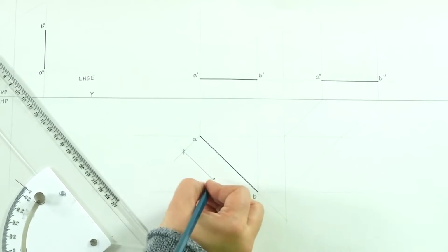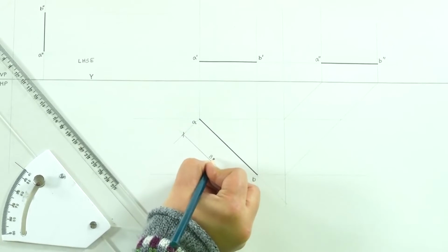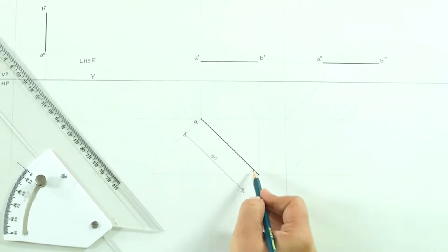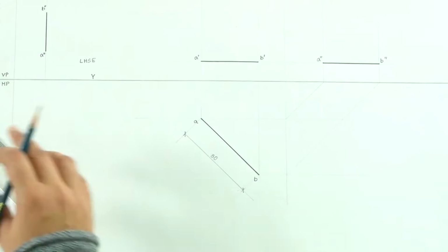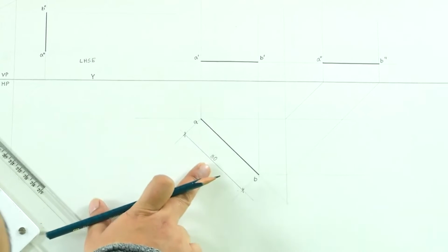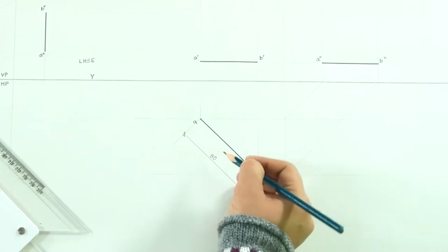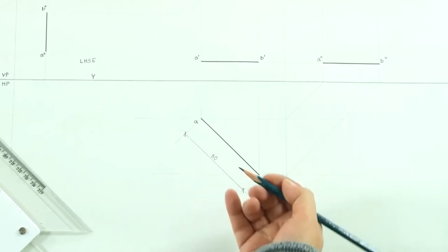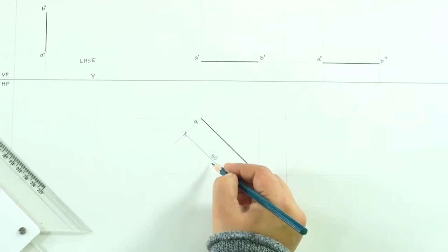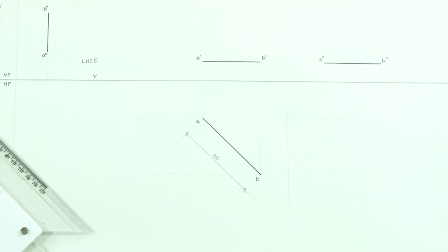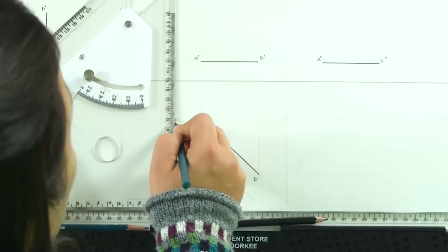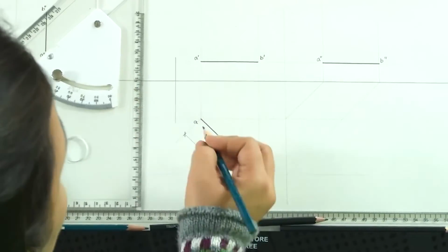So, that is why in this case we will be mentioning the dimensions here in between the dimension line and the actual object, which is a rare thing to do, but in certain cases like this we might be needed to do that. So, if we write 80 below it, that is not correct. If we invert it, then it will be very difficult to read. So, the whole point is about the clarity of the drawing, its readability, and for which sometimes these exceptions may occur. The other dimension, we will mention the other two dimensions.